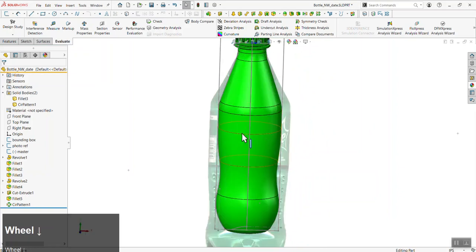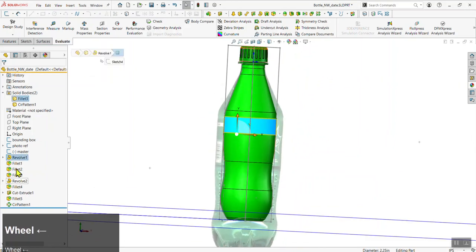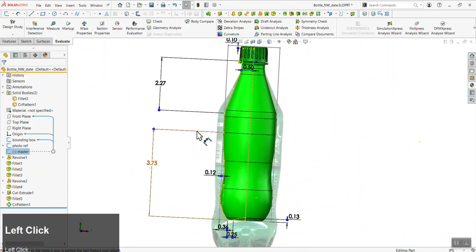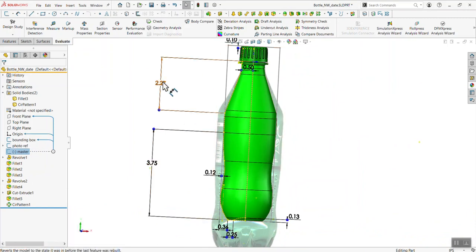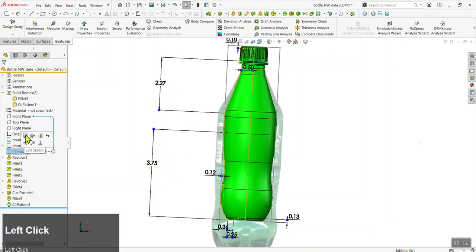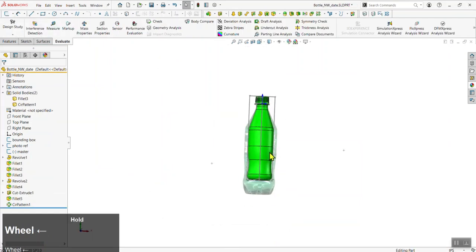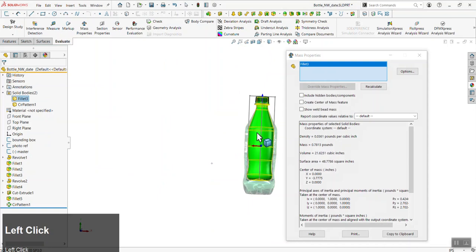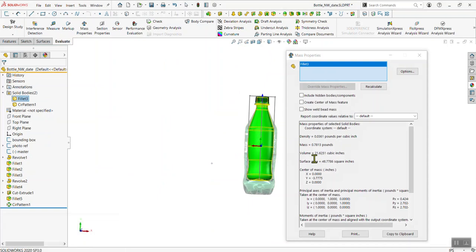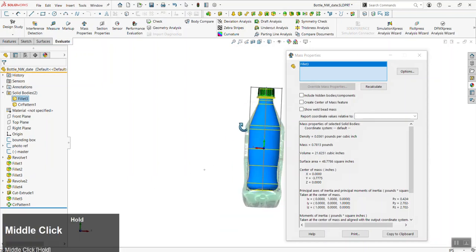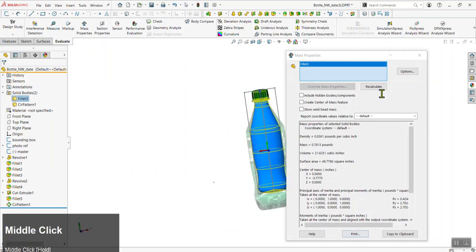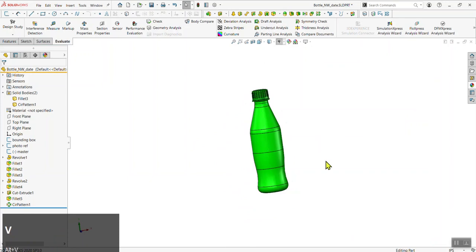Sometimes, we can see here like this label panel got really small because in the master we're having this be fixed. So you can see if the height got smaller than the sum of these two values, we would have an error, for example. And it does sometimes require coming in and manually adjusting this just to keep the design looking similar to the original intent. So this is how you change your model. It's a good idea to practice this early. Here you can see I'm a lot closer. The initial volume was 42. This one's now 21. So I could save this out as like a half volume, or at least one that's close. That could be tweaked a little bit more.